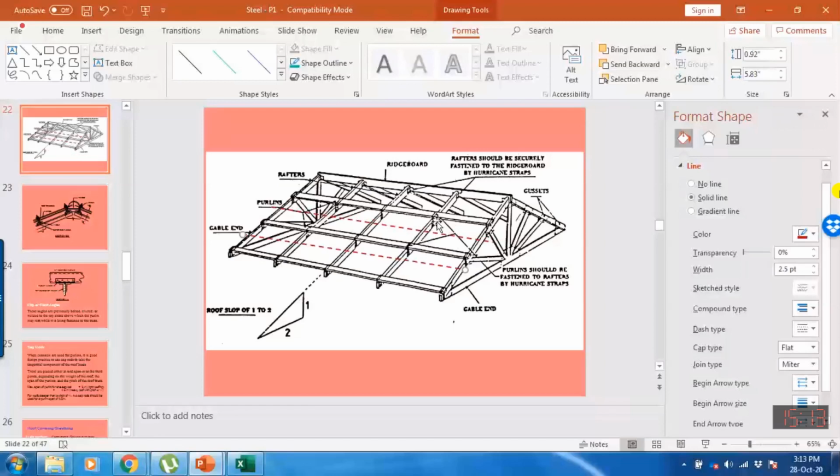This purlin is surrounded on both sides, so it has load from half of the panel length on one side and half of the panel dimension on the other side. The total width supported by this purlin is equal to P: P by 2 on one side and P by 2 on the other. So the areal load multiplied by this width P, the spacing of the purlin or panel length, converts the distributed load to the UDL.